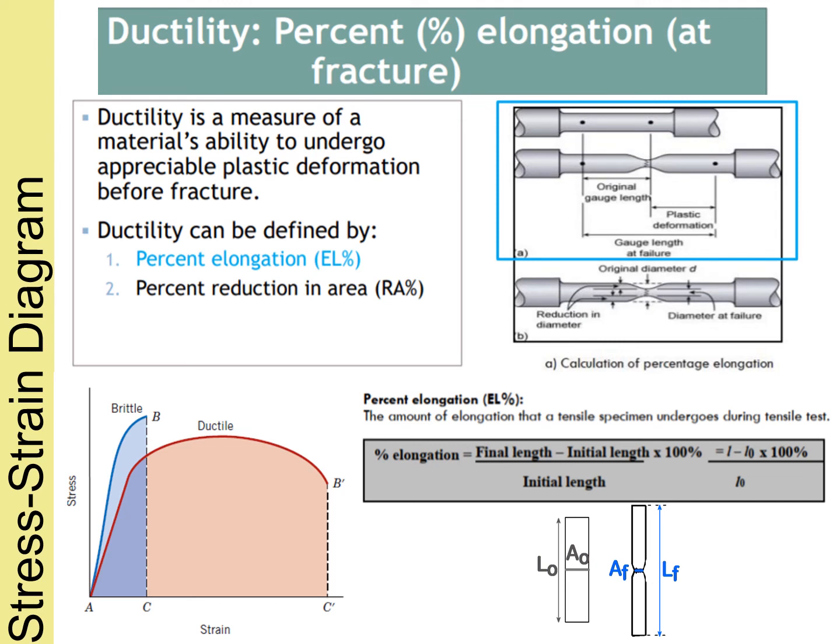The brittle material undergoes little deformation, for example this one, under the action of the load before it fails. Compared to the ductile, it's a massive change compared to the brittle. So from the Callister book, it says that in order to categorize a material as brittle, it is not more than 5% of the fracture strain.